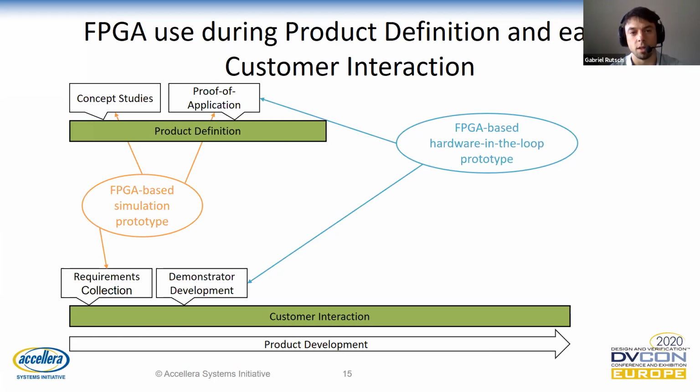On the other hand, on your side, you can have a hardware proof of application, and it's quite convenient. What I showed before, that you can just drag the core that is synthesized on the FPGA from the hardware-in-the-loop prototype to the simulation environment. You can also do this the other way around. So getting the hardware-in-the-loop setup up and running doesn't imply additional modeling efforts. This is different if you started from a CPU-based environment, because there you don't need to make sure that the model is synthesizable.